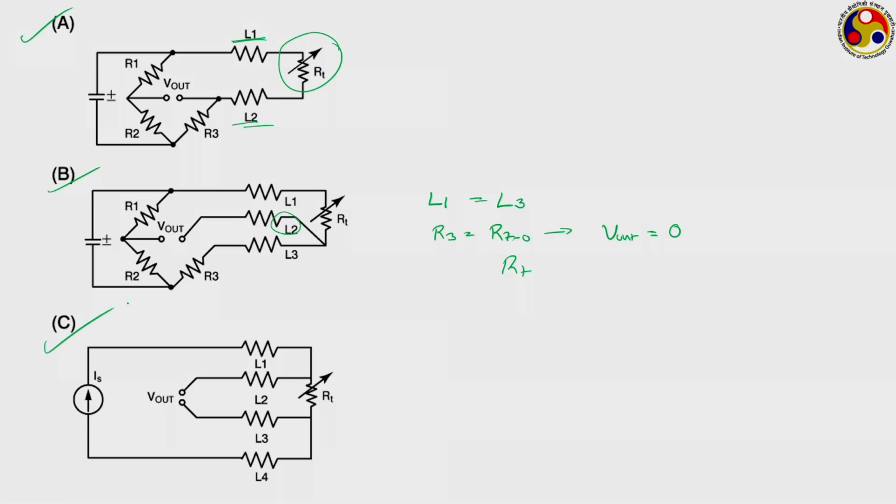This is an even better configuration, it is called a 4-wire configuration, definitely more expensive, more complicated, because we have to include 4 resistors, but this is the optimum configuration. Constant current flows through L1 and L4, whereas L2 and L3 are connected with the actual sensor to give the corresponding output voltage. The lead wire effect of L1 is cancelled by L4, the lead wire effect of L2 is cancelled by L3. So, a highly stable response we can get from them without too much lead error. So, these are the resistance temperature detectors or RTDs.